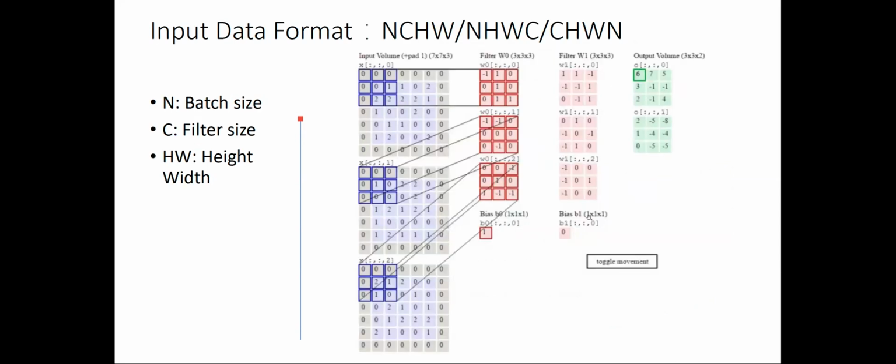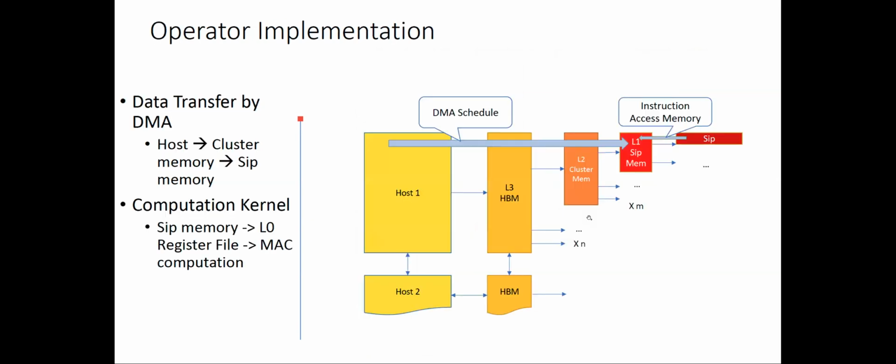And for 2D convolution, as you can see, we have huge data reuse when we slide. We need to adopt this kind of data reuse optimization within our computation kernel as well. That's how we first save off-chip bandwidth, by increasing the data reuse within a single kernel.